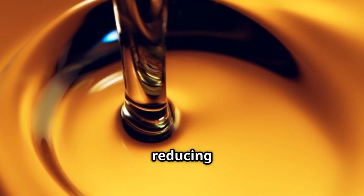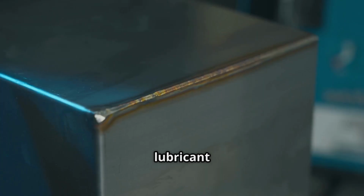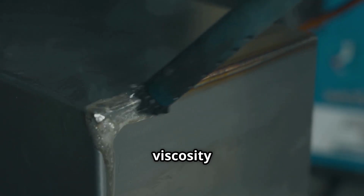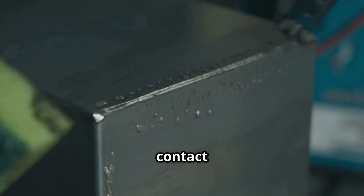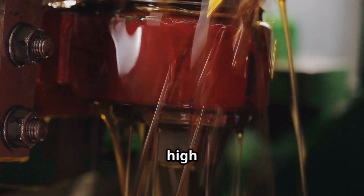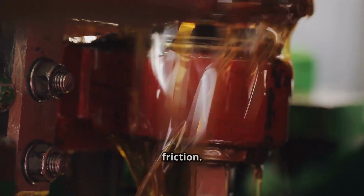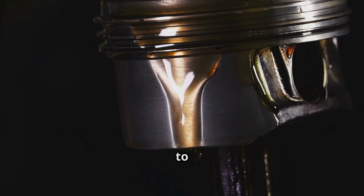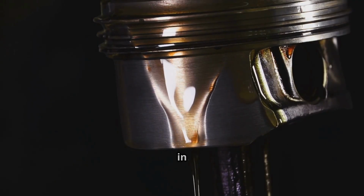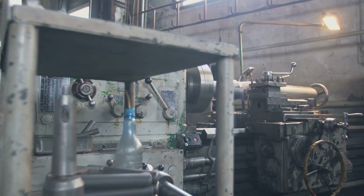A main method of reducing boundary lubrication is to provide the correct lubricant viscosity. A lubricant with too low of a viscosity cannot keep the metal surfaces separated, and metal-to-metal contact occurs. A lubricant with too high of a viscosity will result in an increase in the oil's molecular friction. This internal oil shearing action causes layers of oil to slide past each other and will, in turn, increase operational temperatures and energy loss.